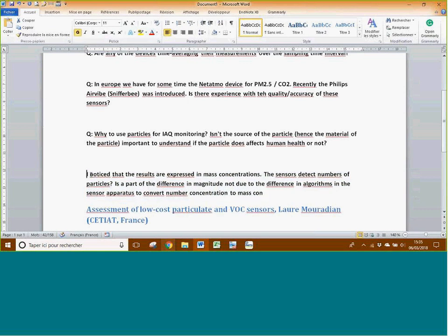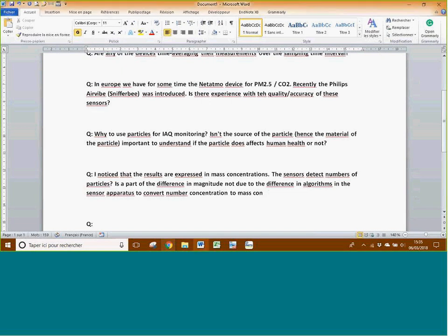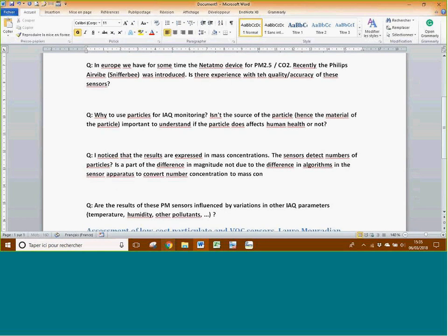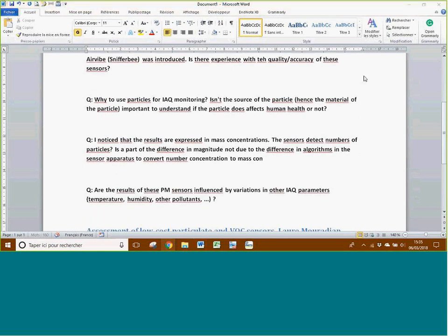We have to bear in mind that, of course, there are other things about sampling times that would be involved here. Let's say you had one of these in your home or an office or what have you, is that there is mixing time in the space between the sources of the particles and you actually detecting it. That adds on another time scale that, of course, varies depending on the building size and the volume that you've got and how far away from the sources that you are.